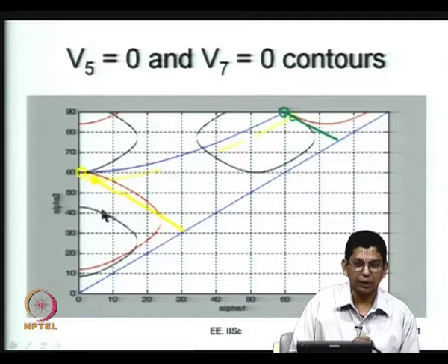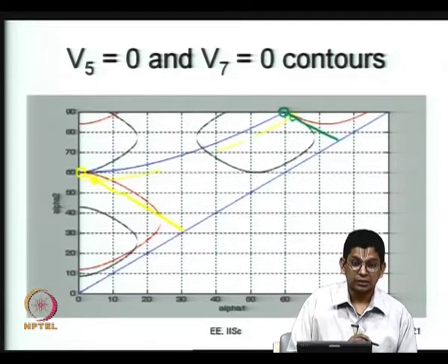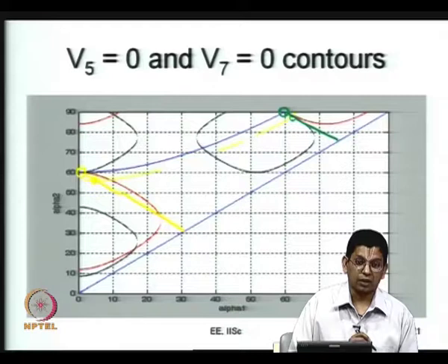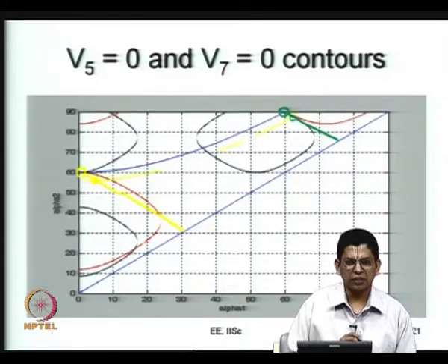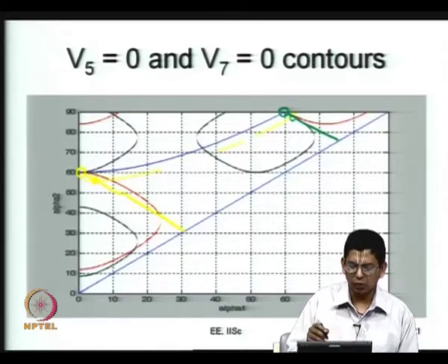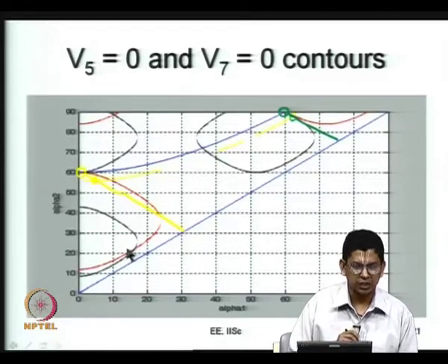So, it is going to lead to a substantial amount of V7 and also a substantial amount of 6th harmonic pulsating torque. So, that is an issue there now. So, you can also consider certain variants. So, this is how you can look at it when you draw all these curves, you know what is necessary.